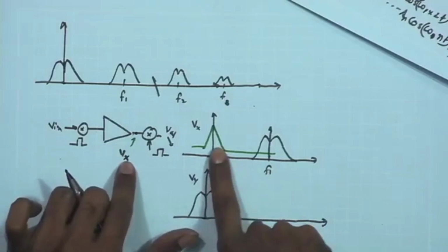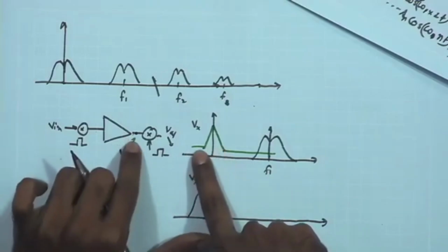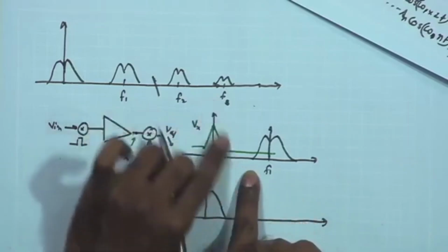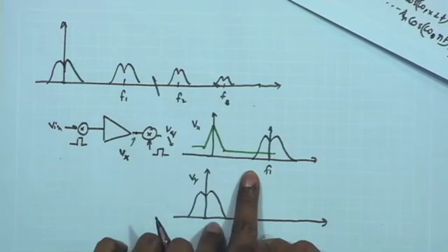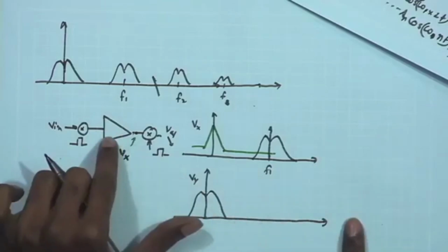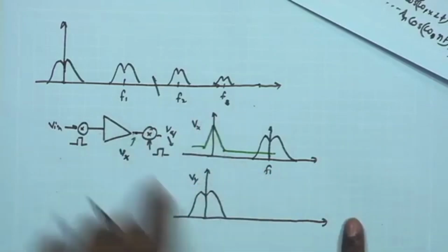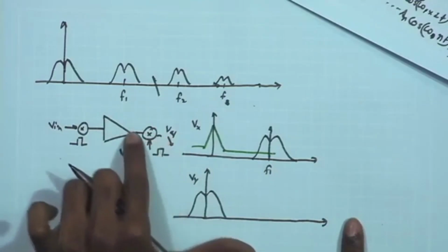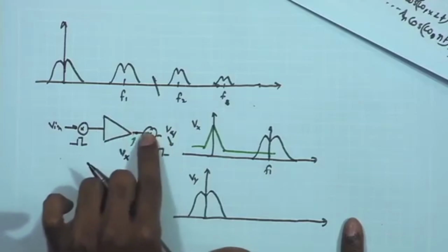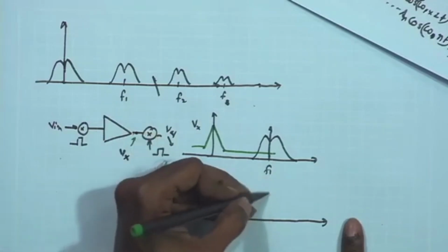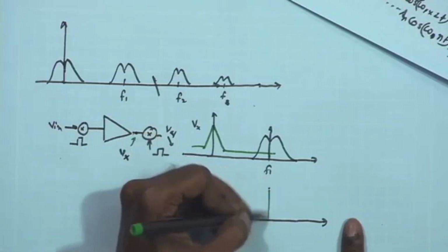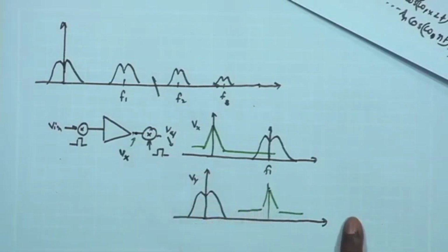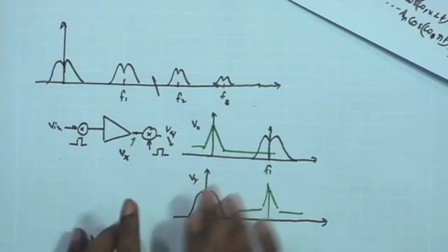And if I look at the 1/f noise spectrum, however, that was sitting over here at the base band or low frequency, it was going much sharper, going much higher at lower frequencies, but now I have basically shifted this 1/f noise to f1 after the anti chopping operation, because for the 1/f noise over here this is acting like the chopping operation. Therefore, this gets shifted to f1, and my desired signal is back at lower frequency.